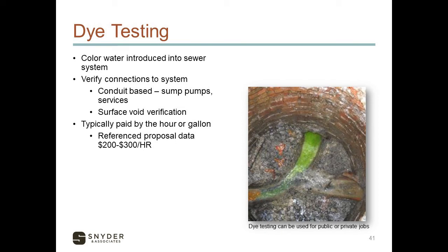We can do that. Commonly, you're going to put this dye in someone's bathroom fixtures and send it down the drain. I have seen it done where we have pumped dye into someone's yard to identify if we do get any groundwater entry into the sewer system. That becomes more difficult to manage from a cost standpoint. We don't really know how much it's going to take, and so that can really run a risk of just running up the actual cost commitment for that type of inspection if that method is needed.